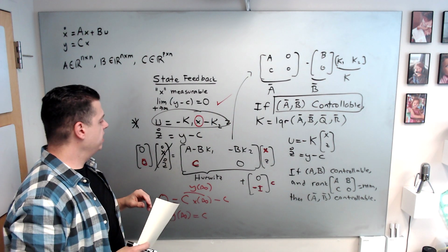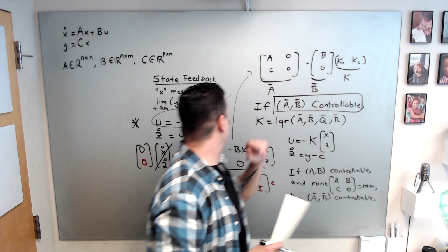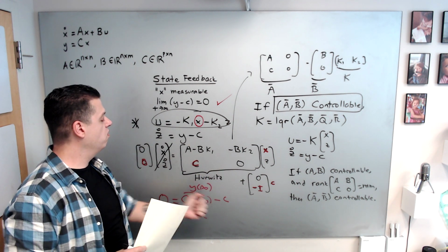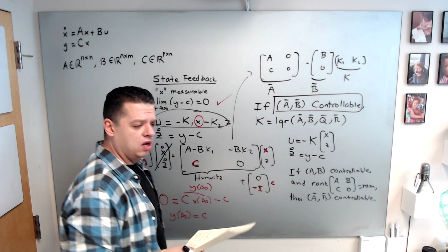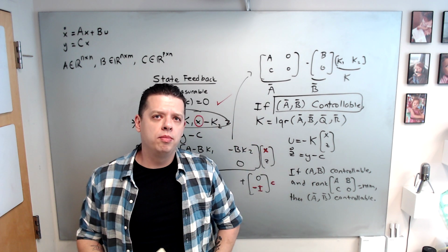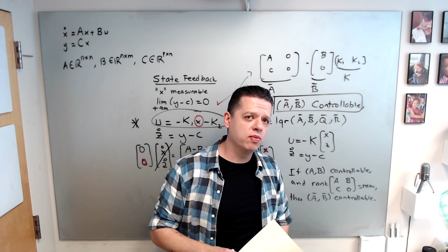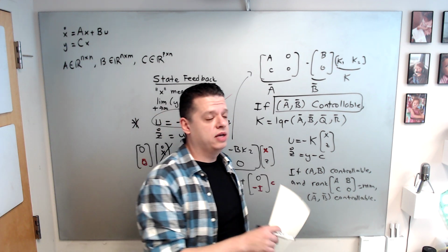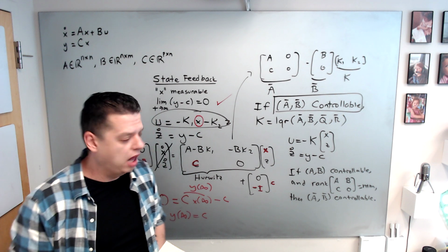To wrap up, basically this is how you choose K1 and K2 together. Once you make this matrix Hurwitz, the system will automatically converge to its equilibrium point. And this integral controller has better robustness to disturbances as compared to the feed-forward approach. So in practice, this is more widely used as compared to the other one. If you like, I can do a proof or something later.